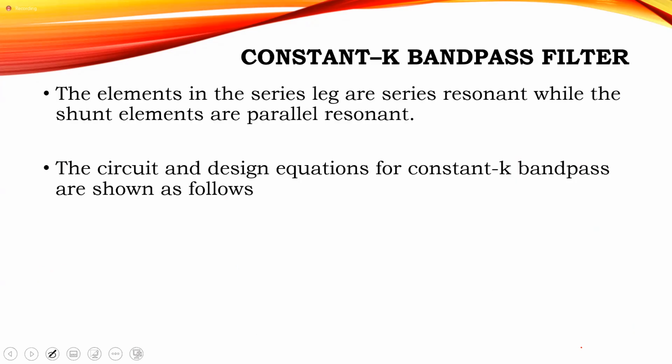So for your bandpass filter, remember now what the convention is. I want a high impedance in series to the frequencies I don't want. All right? So it must attenuate the frequencies I don't want, and that I will put in series.